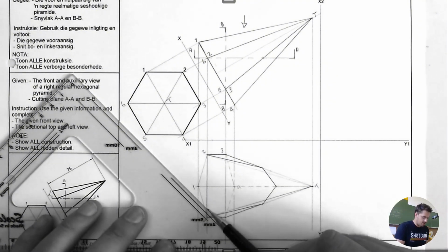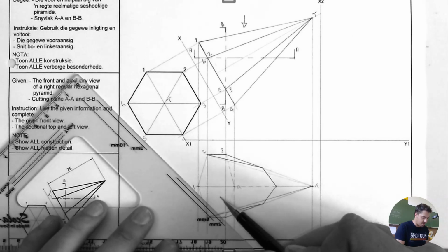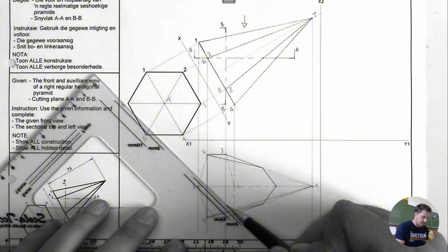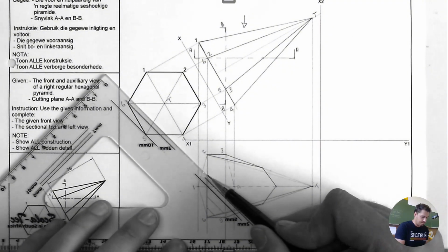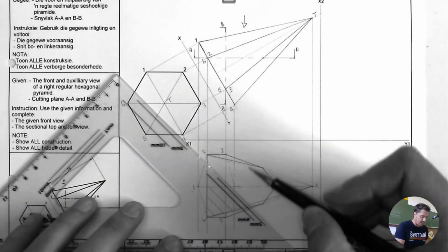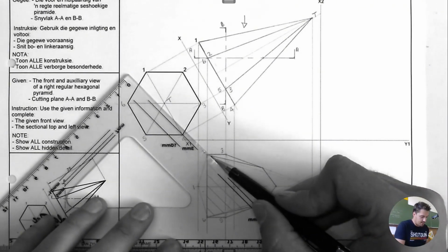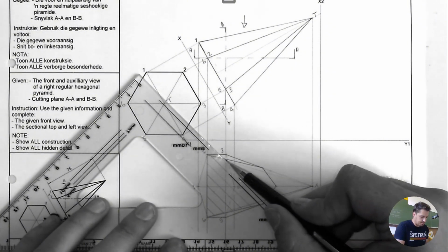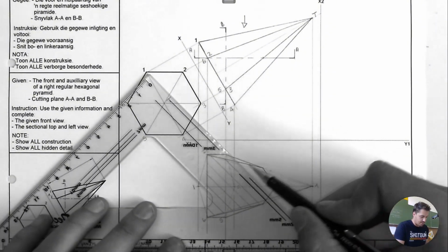All right, so the hatching, sorry, is going to be the same story. We're using a 45 just because it always looks better. There's no rule that actually implies that you have to use a 45 to hatch. We are doing it because in the majority of the drawings, it fits and it does look better.